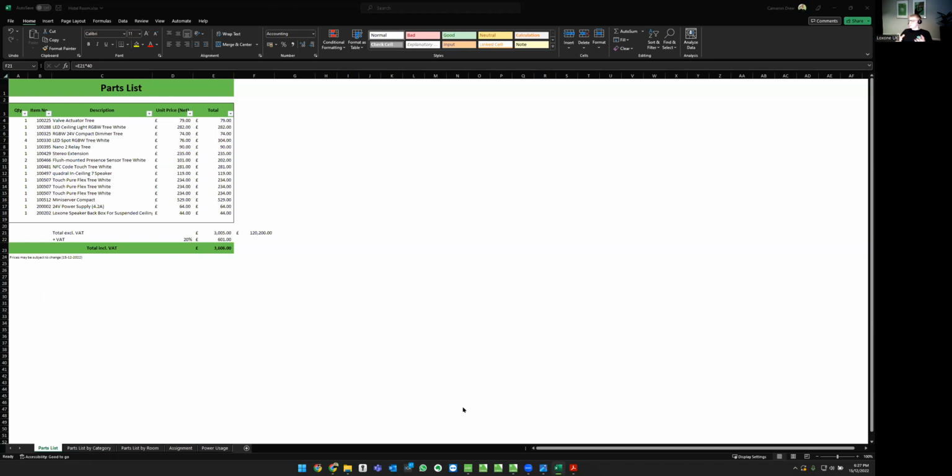So what you could do is dedicate power supply and backups for different areas of the building. You've got 7 fused outputs, and as we've already looked at, we're not using more than 10 amps, and each output is rated up to 10 amps. So you could use an output for each hotel room. That would give a clear indication to the hotel owner how much energy and how much power each hotel room is using at any one time, giving that full visibility.